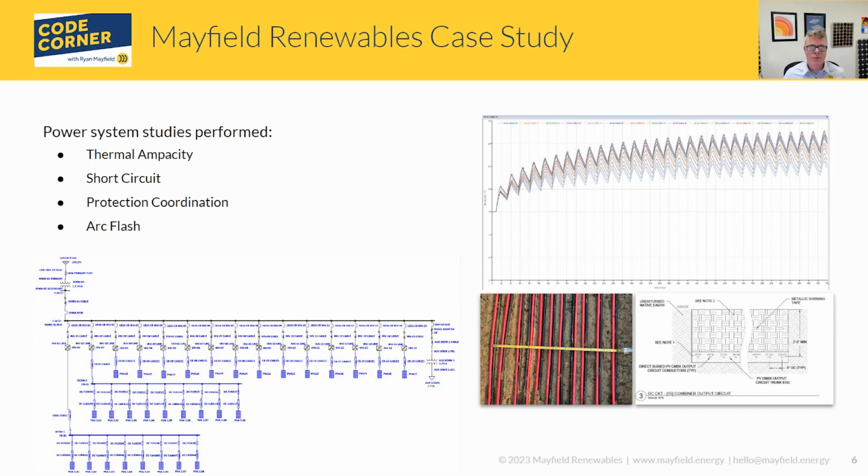Doing some calculations based on conductors in underground: how are they going to heat up based on the soil that they're placed in, the arrangement that they're placed in, things like that. So it comes into play with the conductor ampacity. How big do the conductors need to be, and all of these things come into play. So that's part of doing these studies and looking at those, as well as the short circuit, the arc flash that we talked about, and of course those coordination studies.